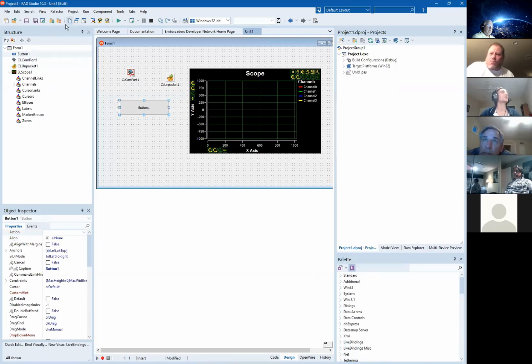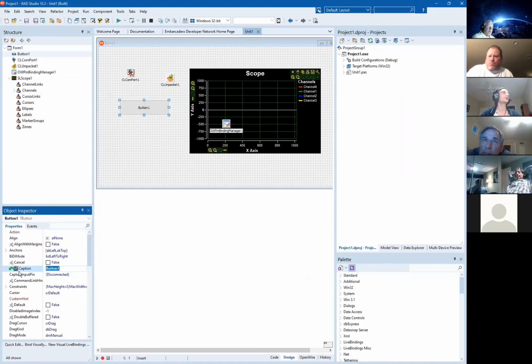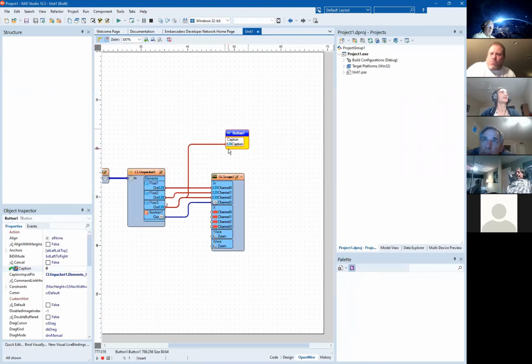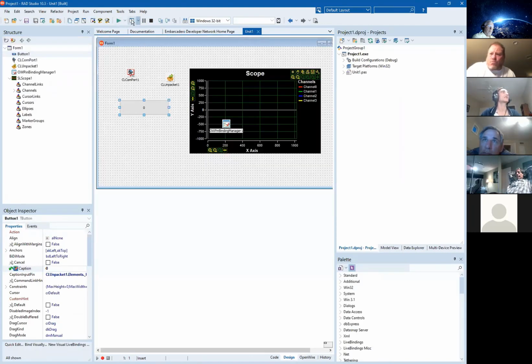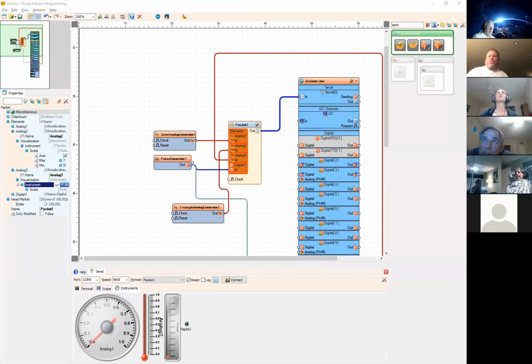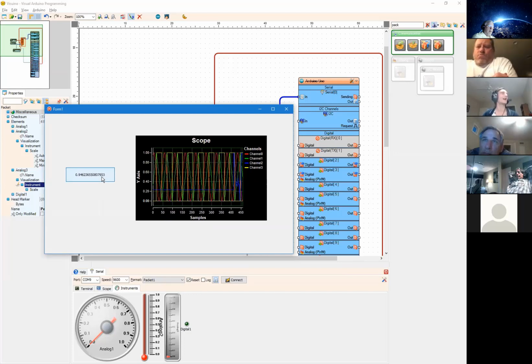Let's say we want the caption of this button to reflect a value that arrives from the packet component. So I can come here and with my OpenWire Visual Live Binding, I can add a sync pin to my caption property. I can come here and connect this. Why don't I use the analog pin and connect right here? And let's see if this works. Let's run it again. I'm sure it's going to come on the wrong monitor again, but that's live when you do live presentations. And Delphi itself moves to a different monitor, but that's okay. Do you see this? The caption of my button reflects the analog value I'm touching at the moment, as it comes from the Arduino.